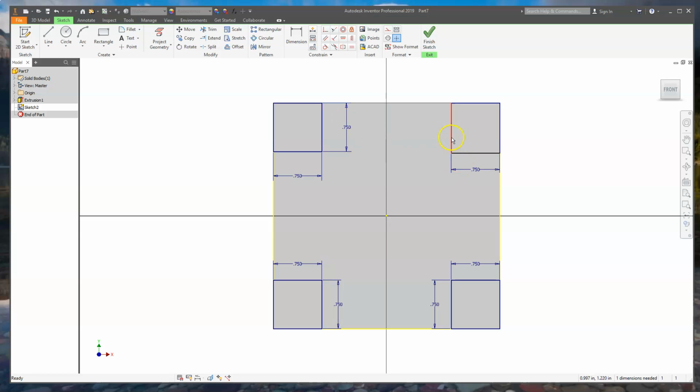On this one I didn't put a dimension on here, but watch this. I can go in there, select the dimension command afterwards, put the dimension on there, and it shows that it's not quite the dimension I want. Type that in now, 0.75, and there we go. Now I have everything resized. All those legs have the correct geometry shape, or geometry dimensions.